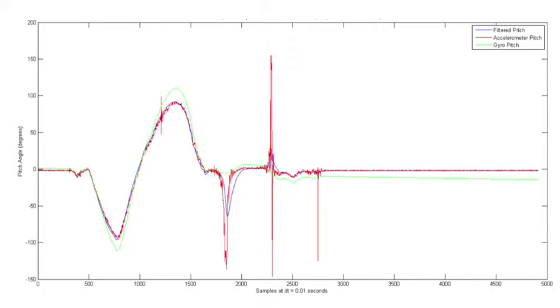You can see that in the report. And then the alpha value that I calculated was 0.985, and I took some readings and rotated it through the axis. And then you can see here the blue line is the filtered pitch, and you can see that towards the right when the IMU is placed flat, the gyro starts to deviate from the rest of the information, and that's due to gyroscopic drift. But you can see the blue filtered pitch hugs the accelerometer, the red value, and so gyro drift is completely eliminated.